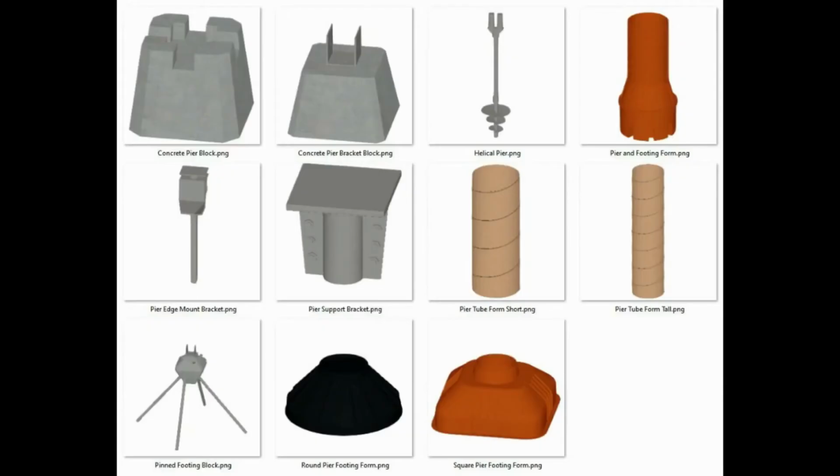Forms for a pier foundation. Piers may be square, rectangular, or round. Piers that are to be square or rectangular are formed with 2 short sets of wall forms. These forms may be built in place, or they may be prefabricated panels.